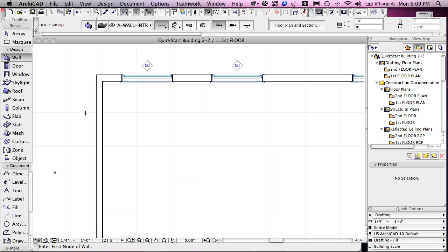Now if I go to the edge of the wall here, you'll see this is the 10-foot snap point, but that's measuring on the outside. If I go to the inside, you'll see a snap point measured. Let's just compare them. You can see that there's one here and one there. This is the one that's 10 feet clear space. So you should definitely measure along the edge that will give you the correct or appropriate distance that you need. Now I'm going to click to start placing this wall.